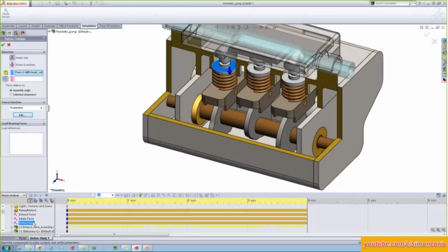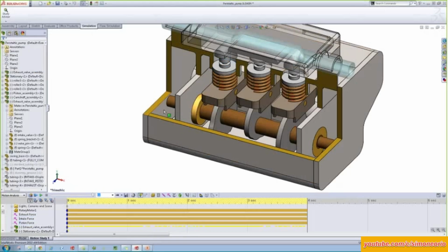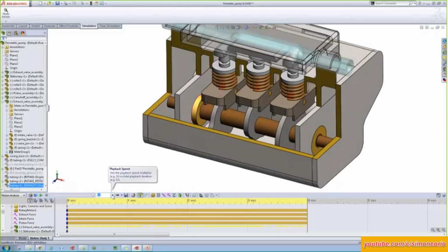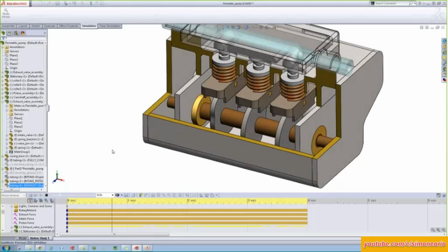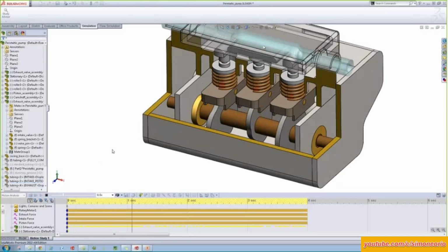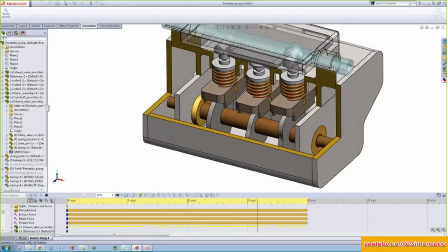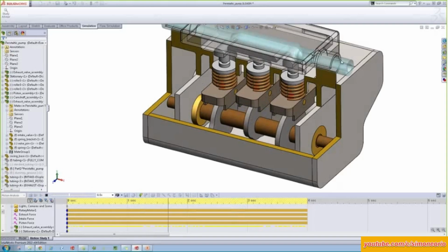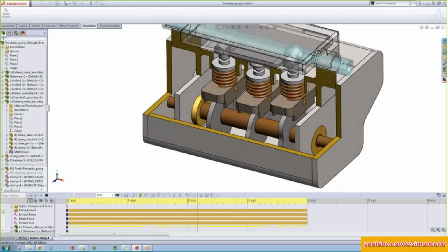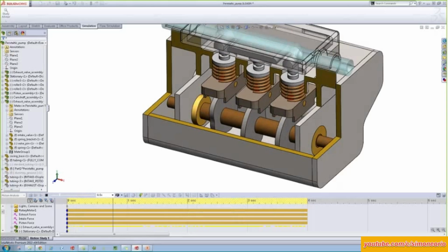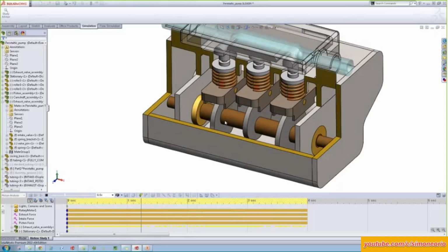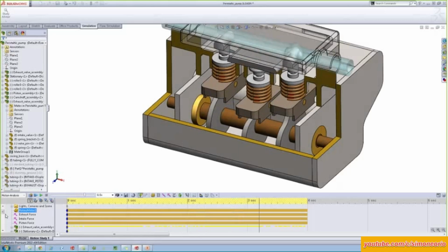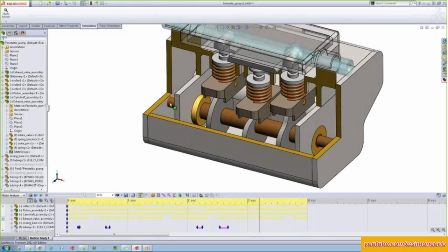Okay. And then what we want to know is the torque it's going to take to go through. Let's play it about half speed here. Play through it again. We'll loop it. The force that it takes to compress this tube is well known too, so we added that to the equation as another variable. So we know the movement that we want. Now we want to know what kind of torque is it going to take to move this assembly down here to push those.